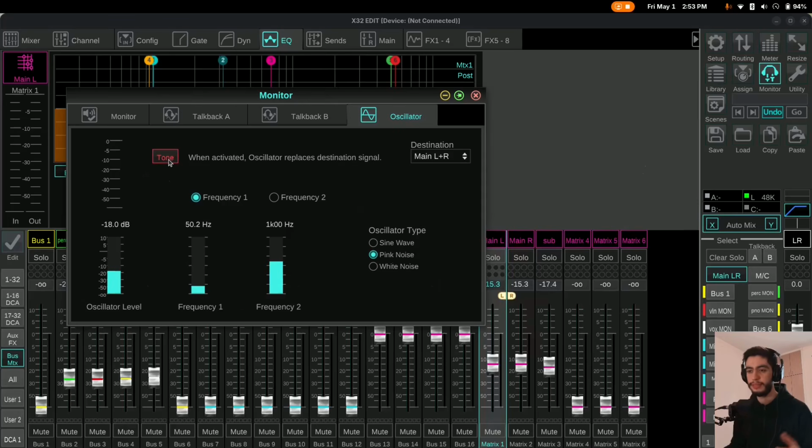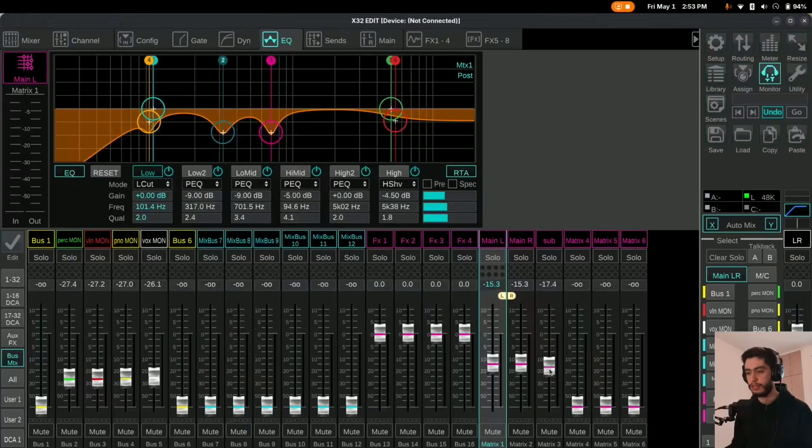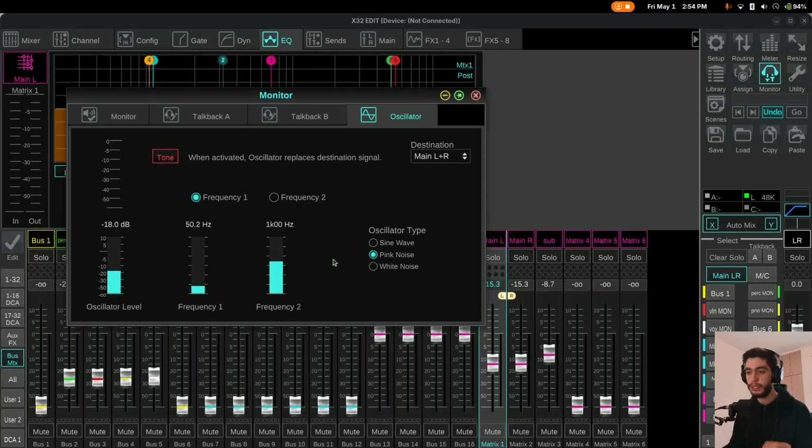So I might be sending pink noise like that to the subs and turning them up, up, up. Now I feel like it's loud enough and they are now louder than the main speakers, but I cannot perceive that because it's hard to do that with pink noise and your ears. So then the band starts playing, or I have playback music and the bass is really loud. So if you don't have measurement software, use a sine wave at 50 or 60 Hertz and turn it on and off very quickly to gauge how loud they are, and you set them like that.